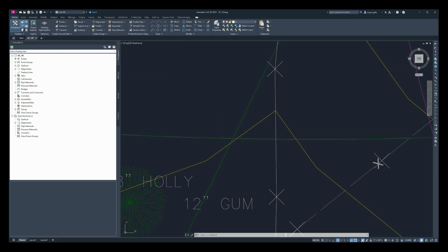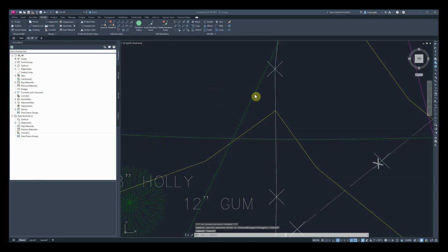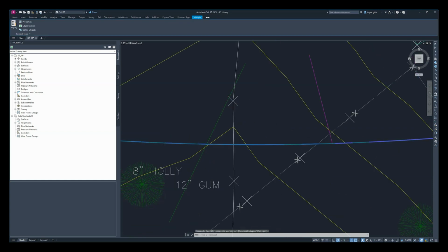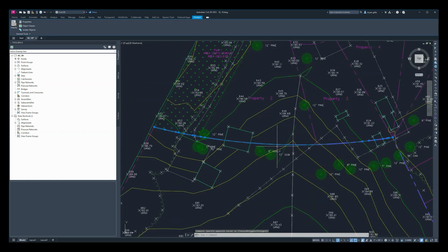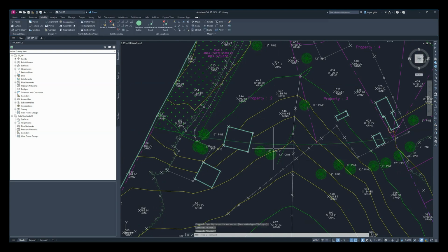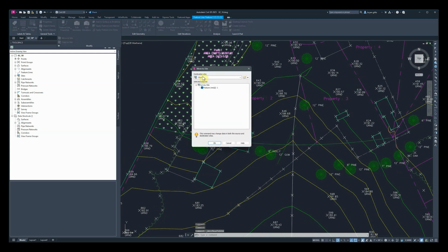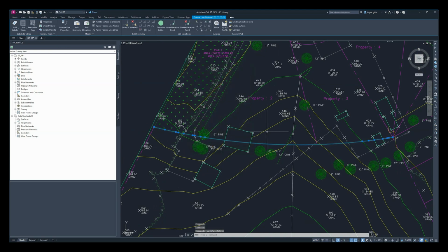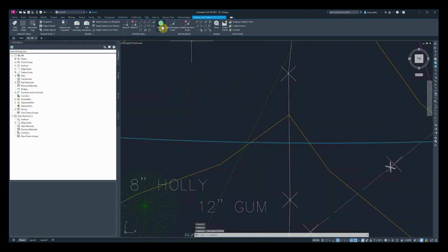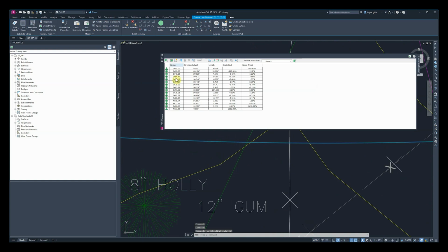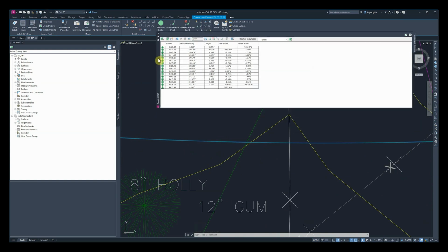my mind's blanking, one moment. We want to go back to moving these to a different site. So let's select our original feature line again. I have multiple selected, so click that feature line. We're going to go back to Modify, we're going to Move to Site one last time, and this time we want to send it back to the none site, so we want to remove it from all sites. And again, just to really belabor the point here, we now see that that point for that intersection is no longer listed as a station.